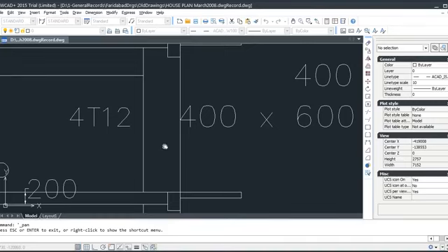This is acceptable because this height does not segregate, does not separate your stone aggregate and your sand. Concrete remains as you mixed it, the grain mix doesn't break during pouring. And if you drop from here, it will break. The mix then has no meaning in that case.